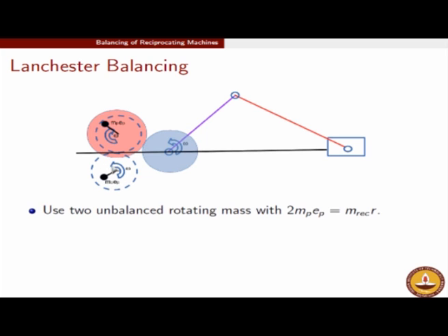These two unbalanced masses are going to add up along the x direction, which is the direction of slider motion, but these two unbalanced masses will in fact nullify each other in terms of the y directional forces. In the earlier philosophy the problem was the addition of the unbalanced rotating masses was creating y directional forces. So here I am not adding a single mass, I am rather adding two counter masses, each of them rotating in an equal and opposite fashion as the primary.